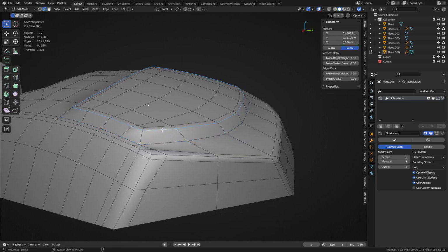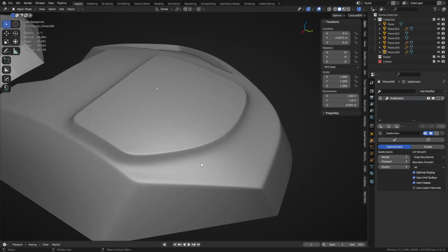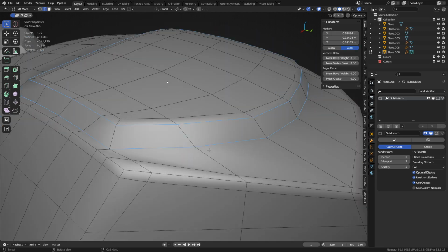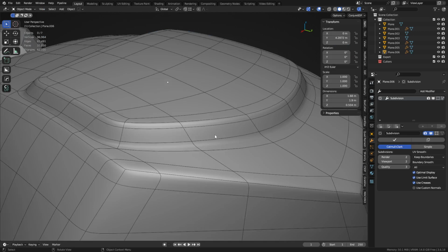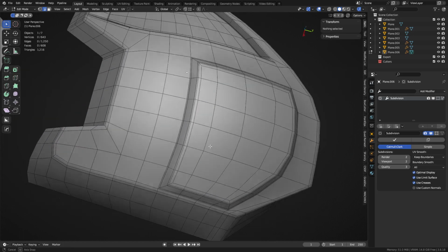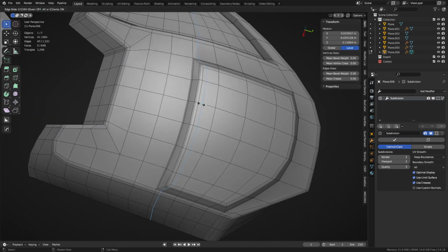You don't have to necessarily do that either. You could just bevel the top perhaps, get it even sharper up there. But on the flip side of that, you could also just do a chamfer. So one segment bevel, and it stays a little bit softer and it doesn't get too crazy. If you ever want to hold some of these edges sharp, you loop cut just like we did before.